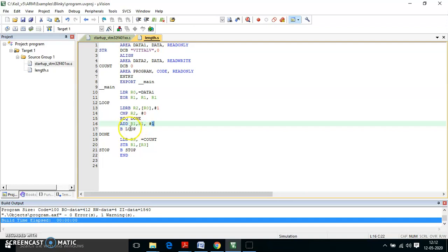Then again we are going to execute the next instruction, B loop. Branch loop means again you are going back to the loop. Again you are going to fetch the next character. So like this the process will continue till it reaches the last character, the 7th character. Once it reaches the 7th character, it will compare, and after executing, again it will go back to the loop. Once it comes here, for the 8th character there is obviously no character, and the ASCII value also will not be present. It will be just default memory window, also 0 0.